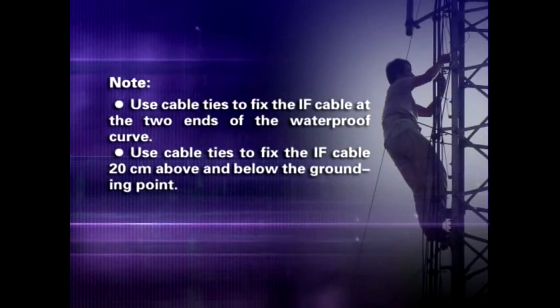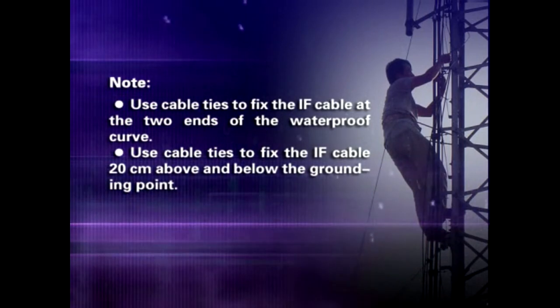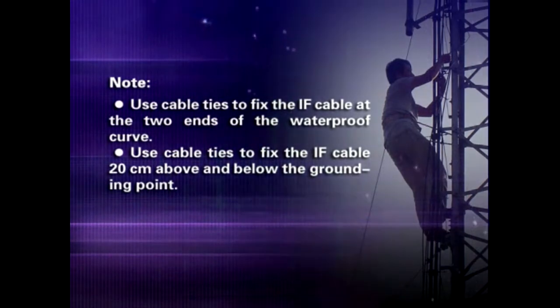Note: use cable ties to fix the IF cable at the 2 ends of the waterproof curve. Use cable ties to fix the IF cable 20 cm above and below the grounding point.